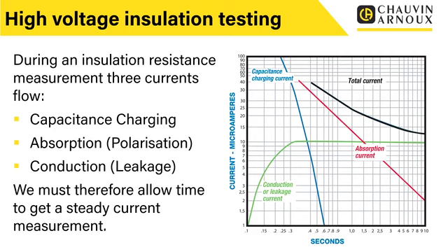We've also got what's called the absorption current or the polarization current. And this is a phenomenon that when you apply a DC test voltage, or suitably high DC test voltage, to this dielectric, to this insulation, there is a certain current flow, and this takes time. This is the molecules within the insulation aligning themselves to the polarity of the test voltage.